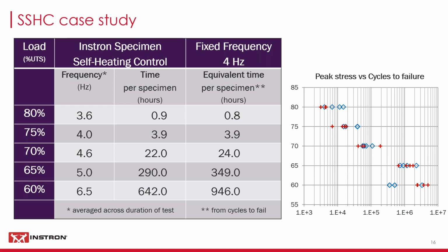You can adjust that stabilization time. If you've got a very responsive temperature sensor, very responsive specimen, you can keep that time window short. If you've got a very noisy signal or a very sluggish, thick specimen, you can lengthen that time window out. What the system does is look at the start of the test. It says, well, I'm trying to get to that temperature. How's the temperature rise looking? If that temperature rise is going up really steeply, the first thing it will do is wind the frequency back down very quickly. The last thing we want to do is overheat the specimen.